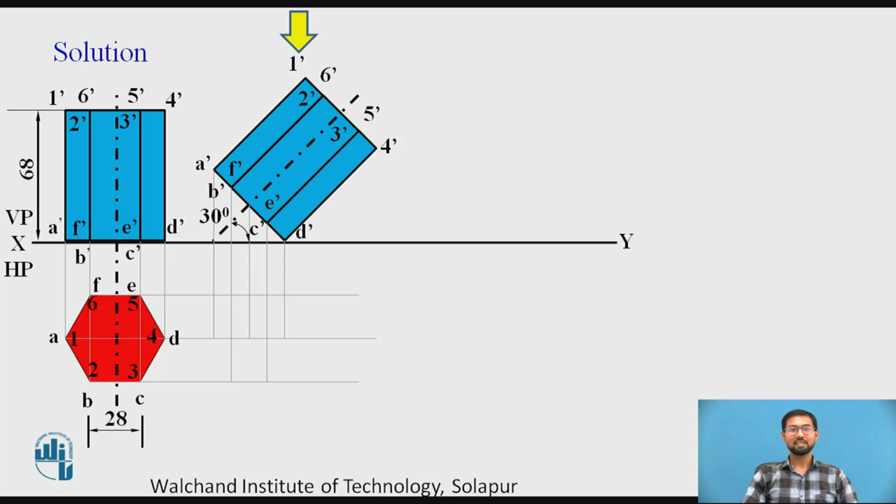Then we get intersection points, and those intersection points will give new points, that is A1, B1, C1, D1, E1, F1. So these are our new points which refer to the bottom base of the hexagonal prism. Then we draw it, and if you observe, the bottom base of the hexagonal prism is a little bit shrunk compared to the first view of our hexagonal prism.